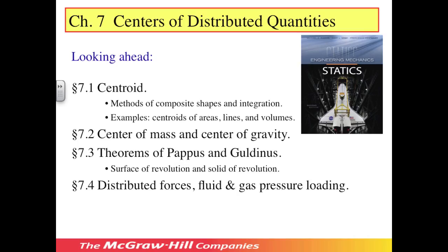The second has to do with the resistance a body offers to acquisition of rotational motion and is called the mass moment of inertia. The area moment of inertia is an important component of the bending of beams under load and is important in mechanics of materials. The mass moment of inertia must be found to understand how long it takes a body to spin up under torque, and so is important in rotational dynamics of rigid bodies.